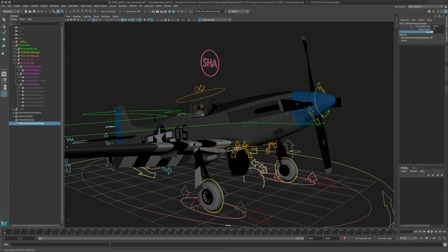You would believe that you could put other values in there, or slow down time, or hook an expression up there, or add some value to your time to maybe read a cache on another frame, or modify time with a float math node or an add double linear. Whatever you do there, you can't change that. Either it's running with the time1 node connected, or it doesn't do anything, or it will maybe load one frame of your simulation if you're reading a cache, but then nothing more. They could just hide it because you can't do anything with that anyway, at least not in its current state.